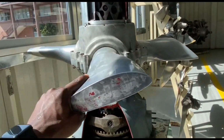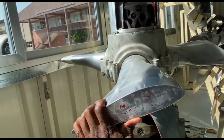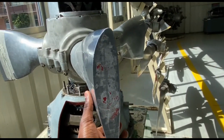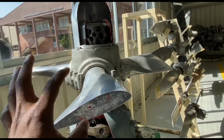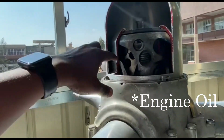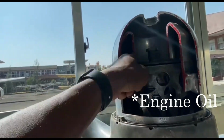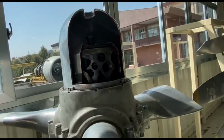We are going to talk about the propeller later, but let me tell you a little bit about this. This is a Hydromatic, and you can change the position from the feathered one. It's a little bit heavy actually, so I have to use most of my strength. This is the normal position and the unfeathered position. This is done by the hydraulic that we connect here. When we send the hydraulic here, it can come here or it can come here as well, in this chamber. We are going to talk about all this later.